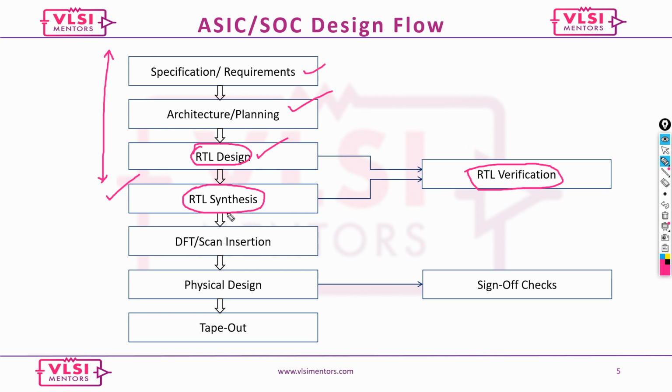Now after RTL synthesis, what is RTL synthesis? Your RTL, the Verilog HDL or SystemVerilog, is in the form of a behavioral model, and that is converted into a gate level netlist, with gates, flops, memories and macros. And there we also do something called gate level verification.